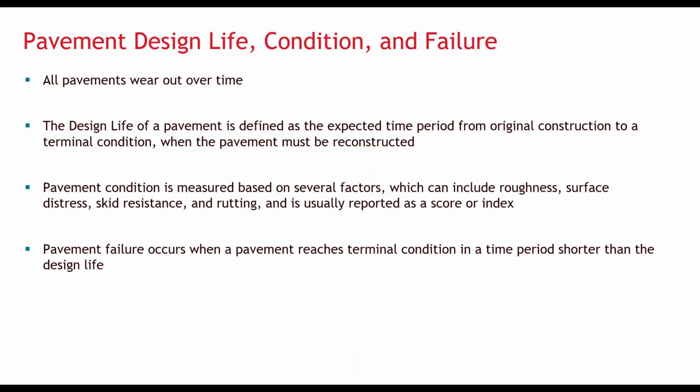This has been a very quick discussion of a complicated topic. I'd like to close the discussion by noting some key concepts relating to how we design pavements and define their performance. First, it's important to remember that pavement design is built on the understanding that all pavements will wear out over time. The design life of a pavement is defined as the expected time period from the original construction to a terminal condition, when the pavement must be rehabilitated or reconstructed.